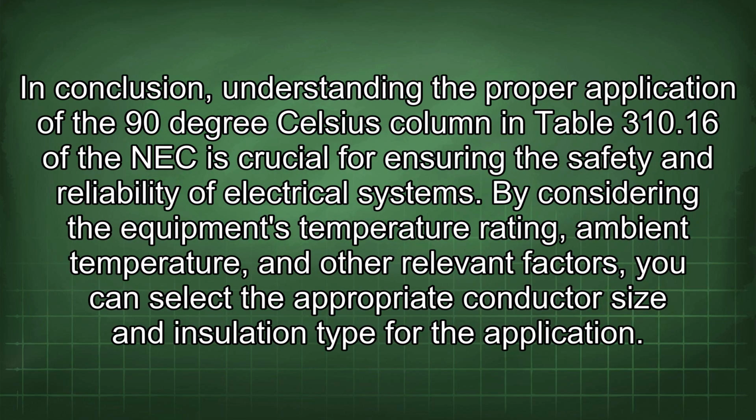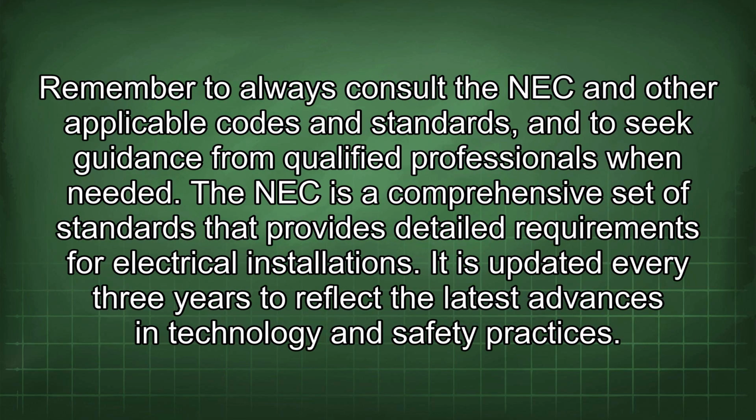In conclusion, understanding the proper application of the 90°C column in Table 310.16 of the NEC is crucial for ensuring the safety and reliability of electrical systems. By considering the equipment's temperature rating, ambient temperature, and other relevant factors, you can select the appropriate conductor size and insulation type for the application. Remember to always consult the NEC and other applicable codes and standards, and to seek guidance from qualified professionals when needed.